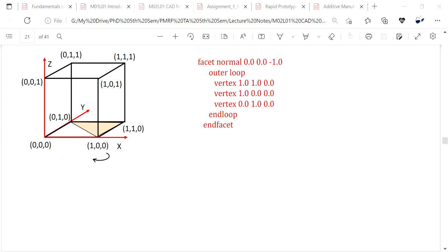So in this way we find out, since it is required in the question that 1 degree angle tolerance is required, 1 is equal to 360 by n. With this, we find out that n is equal to 360, and similarly for all the surfaces we calculate, and finally we get the total number of the triangles.